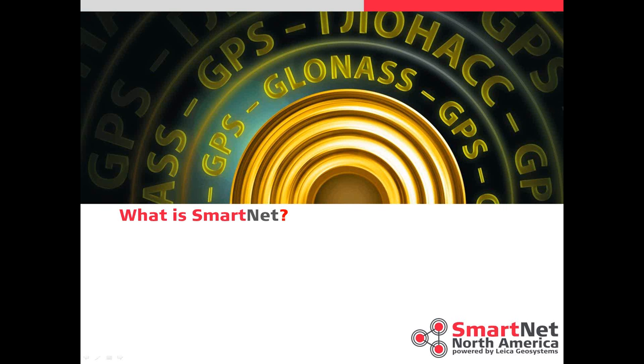Carlos, has there been any tests to verify the difference between 100 epoch measurements and 60 epoch measurements? This comes with a site calibration from existing. The more epochs that you have, the better mean average you're going to have of the motion in the overall GPS position. So that would be, again, personal preference. Again, we're just going off recommended practices that were developed by TSA.